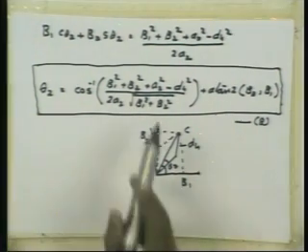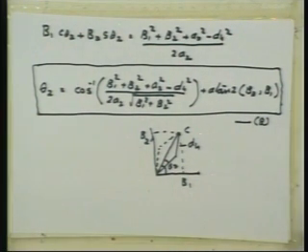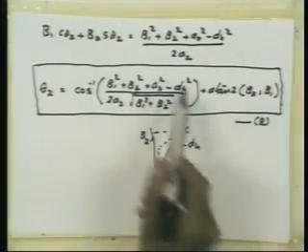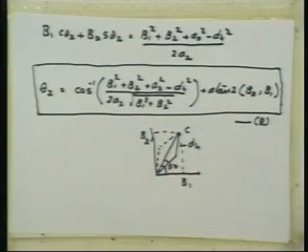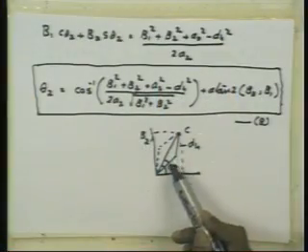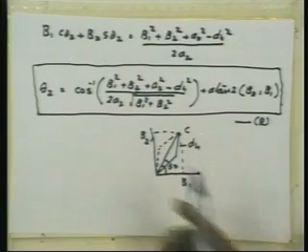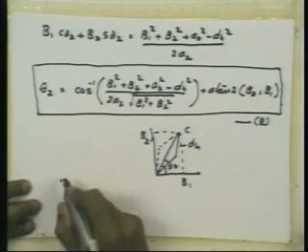So this expression corresponds to this picture. So again there are 2 solutions possibly for theta 2, and when is it that there are no solutions? Well, algebraically, when this particular argument goes above 1 in magnitude, but geometrically, clearly in this picture there is a limit to reachability of these 2 lines, right. They have to be joined always here, and the length is fixed.